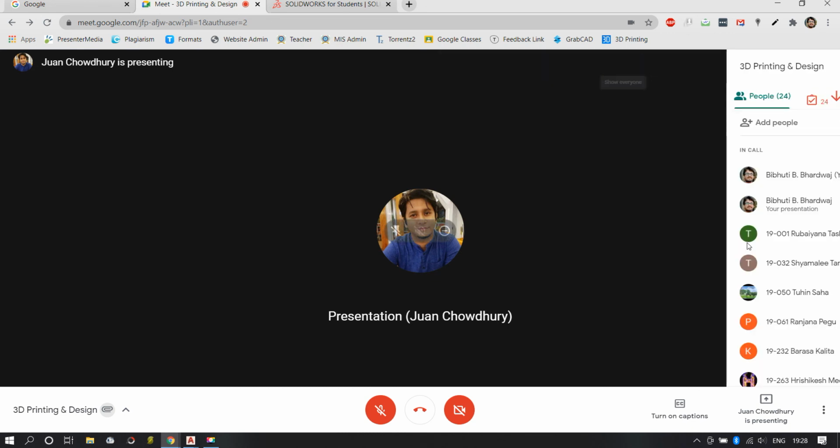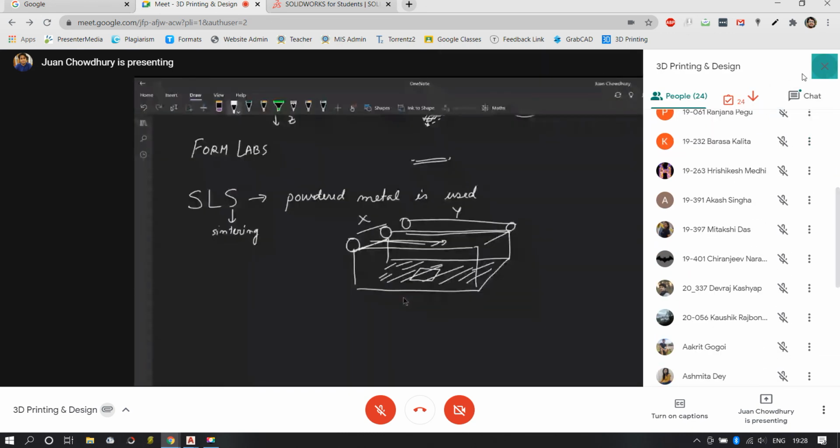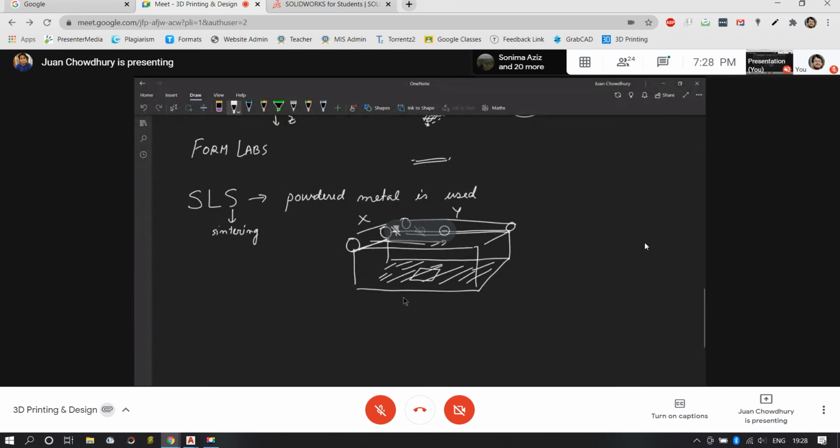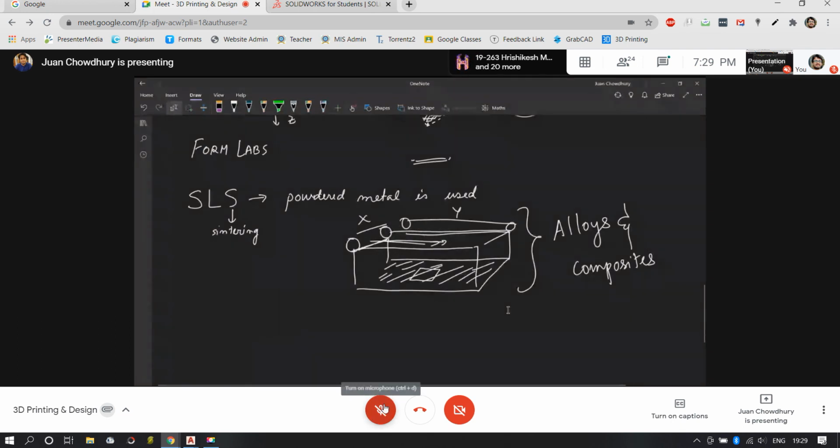All right. Now with FDM processes, this was a little difficult, and with resin also, it will be difficult because 2 resins will mix up chemically as well as physically. But because these are powders, they will not mix chemically or physically unless heated, and heating is what you require afterward. So this has a significant advantage of making alloys and composites. Okay, by the sheer workflow of the system, we are trying to gauge some advantages and disadvantages out of it.